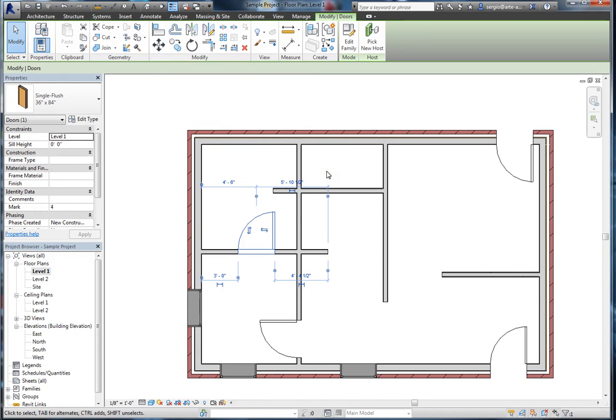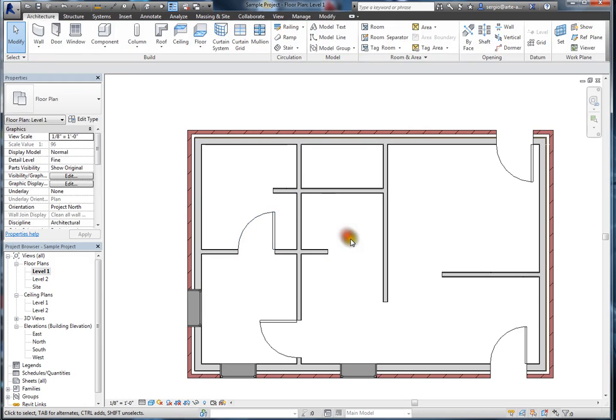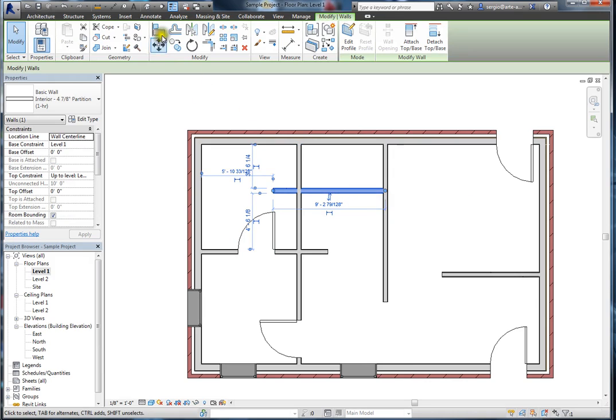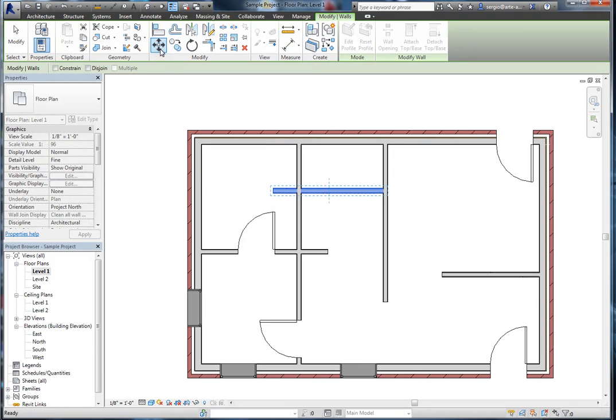Anything that you want to move, you need to select the object first. For example, I select my object wall, and then I click on the Move tool. And then after you select the Move tool, notice that my cursor has a little icon with the same 4 arrows indicating that I'm in the Move tool. Look down here, after I move my mouse away, it says click to enter Move start point. So we have to select a start point of where to move this wall.